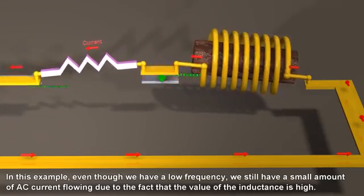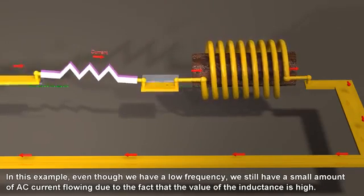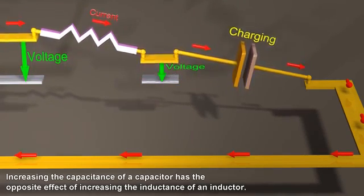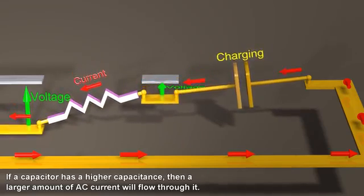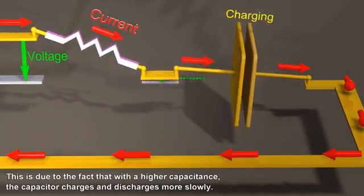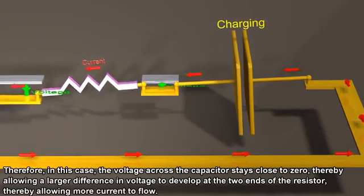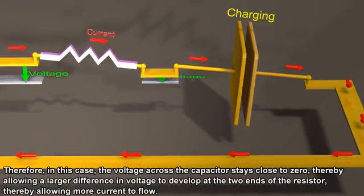In this example, even though we have a low frequency, we still have a small amount of AC current flowing due to the fact that the value of the inductance is high. Increasing the capacitance of a capacitor has the opposite effect of increasing the inductance of an inductor. If a capacitor has a higher capacitance, then a larger amount of AC current will flow through it. This is because with a higher capacitance, the capacitor charges and discharges more slowly. Therefore, in this case, the voltage across the capacitor stays close to zero, thereby allowing a larger difference in voltage to develop at the two ends of the resistor, thereby allowing more current to flow.